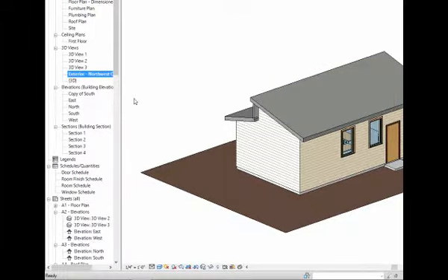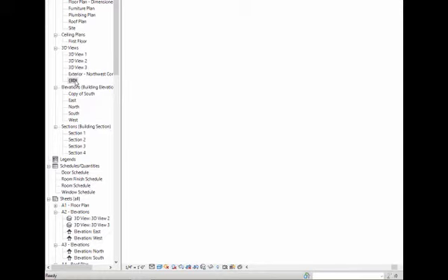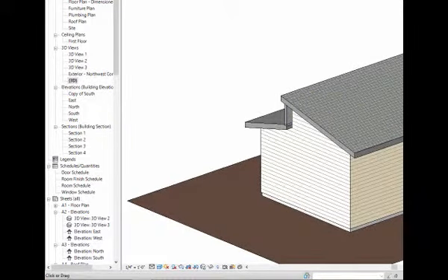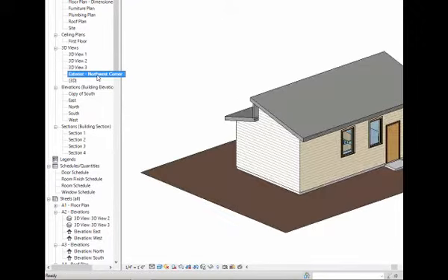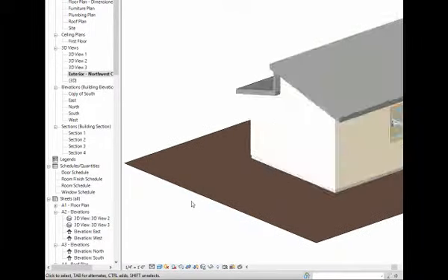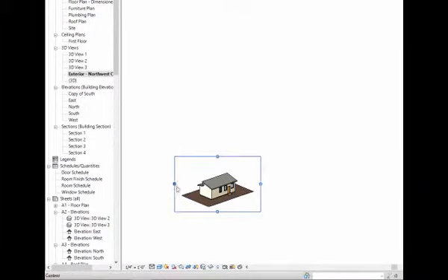The reason I did that is, back over here in the main 3D view, if I rotate that around because I'm working on the building, this view is going to stay locked to that camera position. That's useful because now I can put that on my sheets and I don't have to worry about it accidentally slip sliding around. So think about 3D views. 3D views can be cropped the same way.